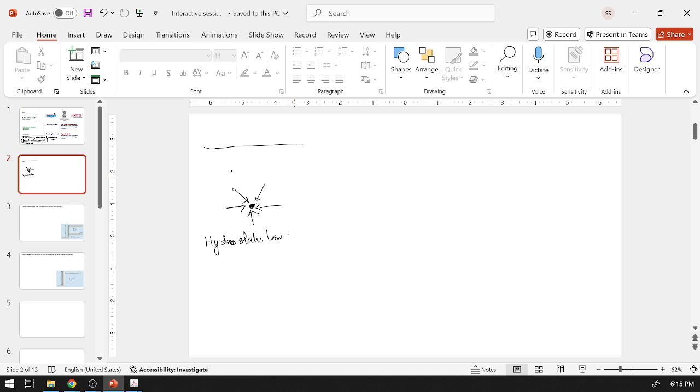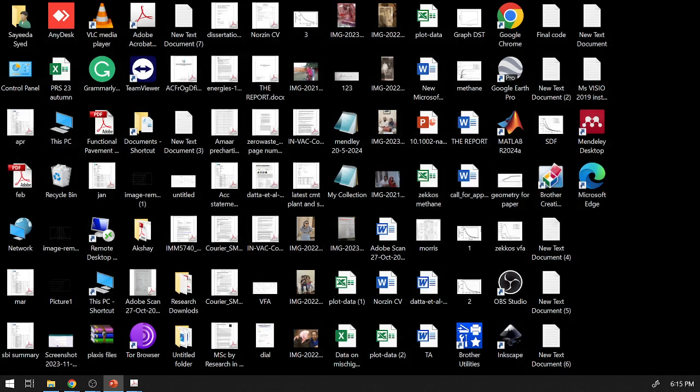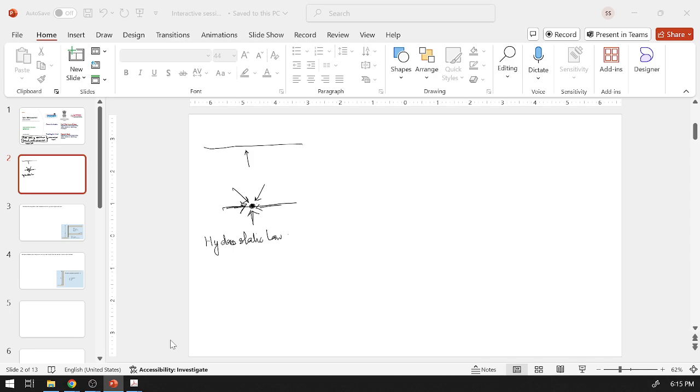Okay, this is the hydrostatic law in which you will experience the same force, same stress from each direction. If this is the depth at which the point you are considering is taken, it is at Z, and gamma W is the bulk weight of water, then this stress will be gamma W times Z. And it will be the same from all directions.